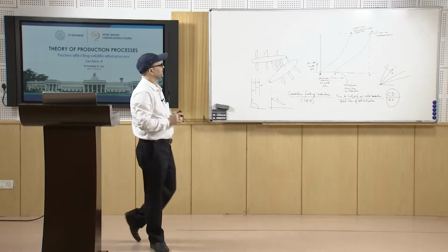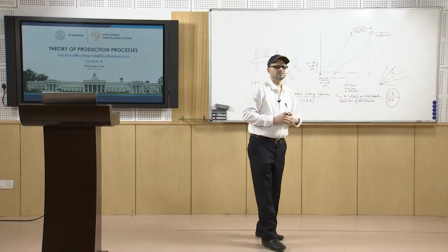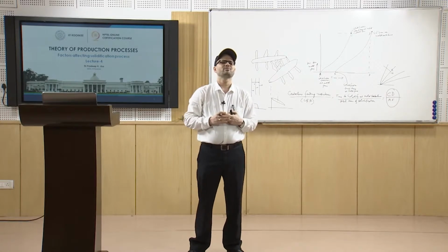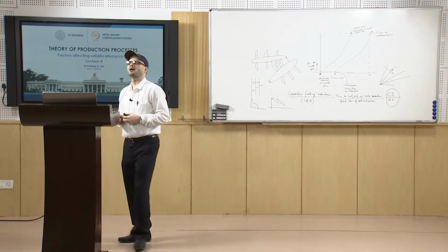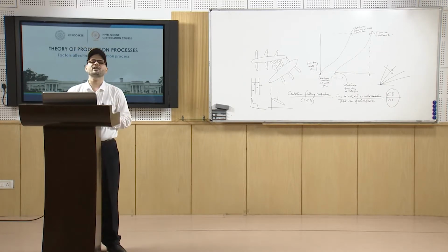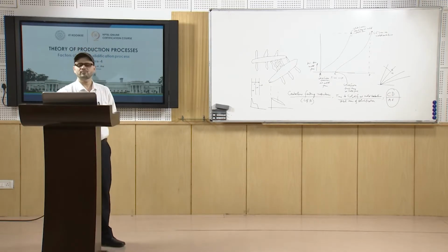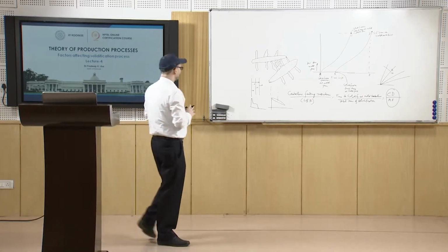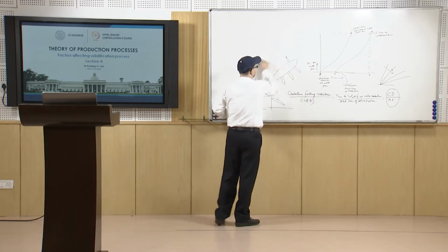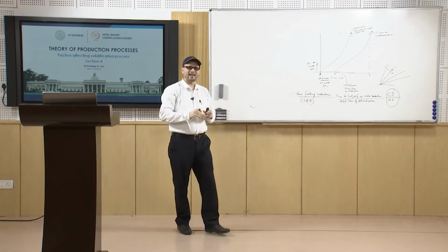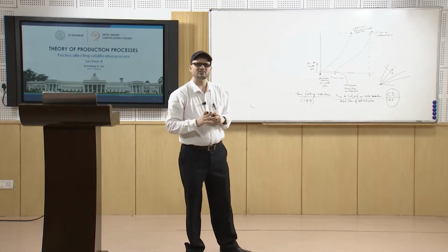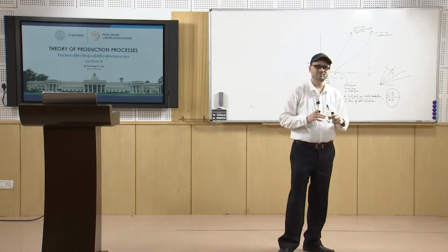Now, why is it important to study this? You will have different variables which affect the start and end of the freeze wave. The different variables are, first, the solidification range of the alloy. If the solidification range of the alloy is more, in that case the separation will be increased. As discussed, if the alloy has a large solidification range, there will be larger chances of the problem of feeding it.